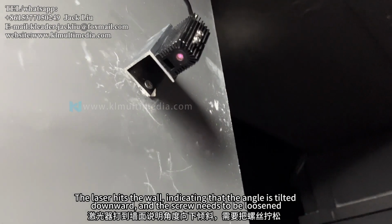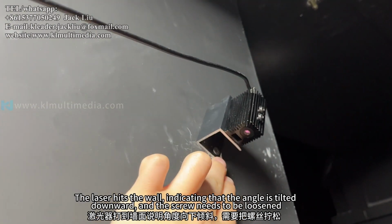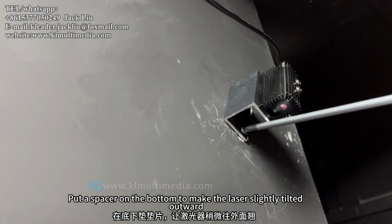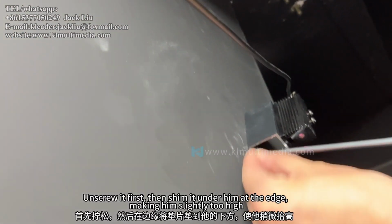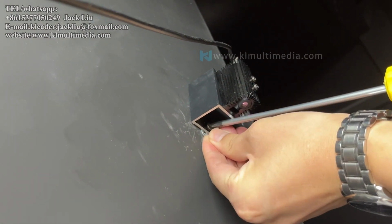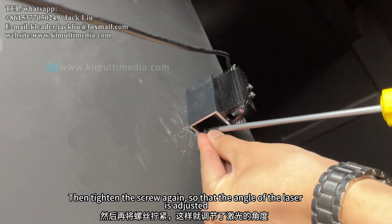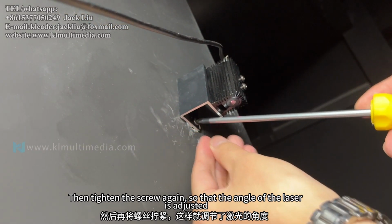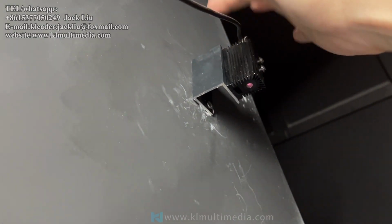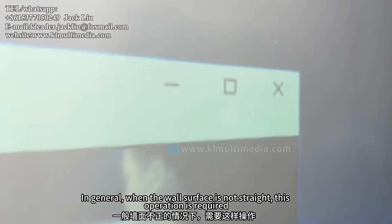The laser hitting the wall indicates that the angle is tilted downward, and the screw needs to be loosened. Put a spacer on the bottom to make the laser slightly tilted outward. Unscrew it first, then shim under it at the edge, making it slightly higher. Then tighten the screw again, so that the angle of the laser is adjusted. In general, this operation is required when the wall surface is not straight.